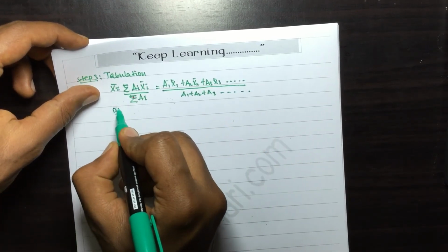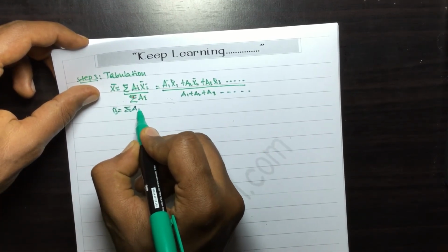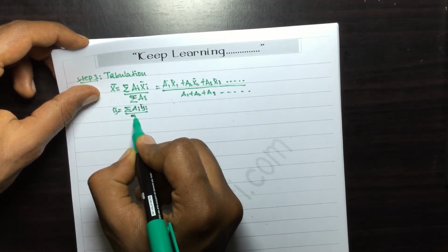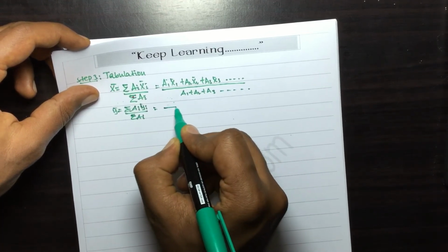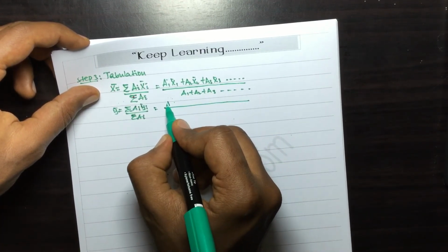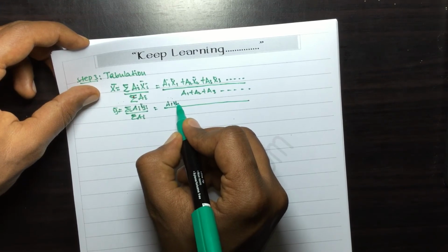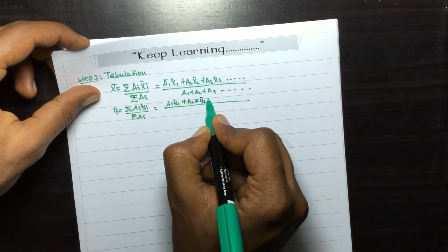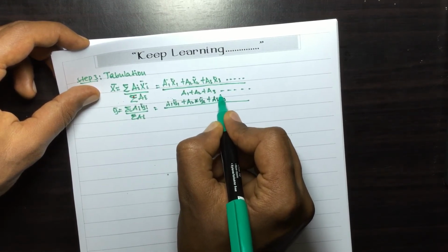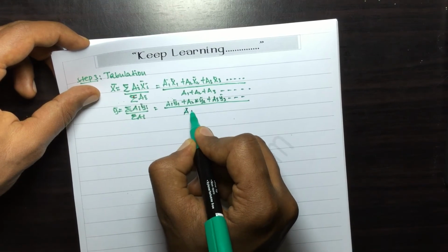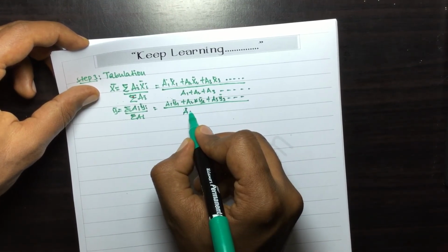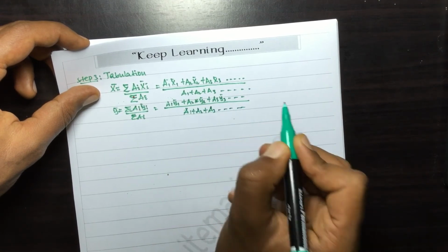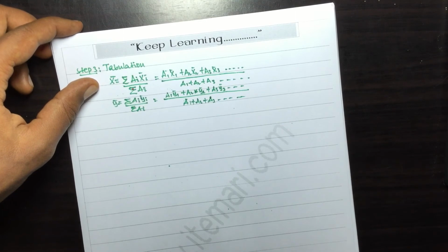What about y bar? y bar will be the summation of individual area times yi over the summation of area, from the superposition principle. Therefore a1 y1 bar plus a2 times y2 bar plus a3 y3 bar and so on, divided by the summation of the areas a1 plus a2 plus a3. It will continue like this.